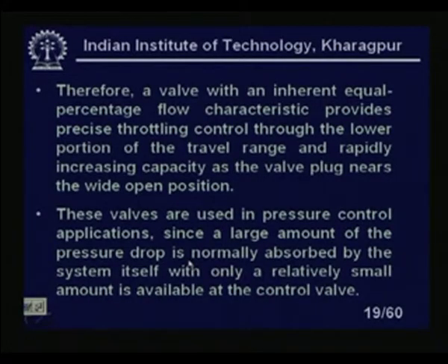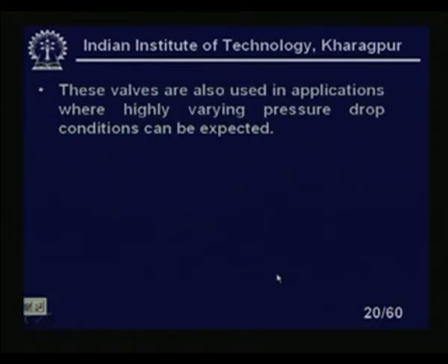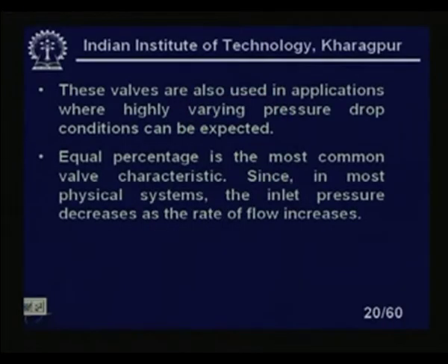These valves are used in pressure control applications, since a large amount of pressure drop is normally absorbed by the system itself, with only a relatively small amount available at the control valve. These valves are also used in applications where highly varying pressure drop conditions can be expected. So there are different applications where we are using different types of control valves. Equal percentage is the most common valve characteristic, since in most physical systems the inlet pressure decreases as the rate of flow increases. So it will be suitable for that type of application.